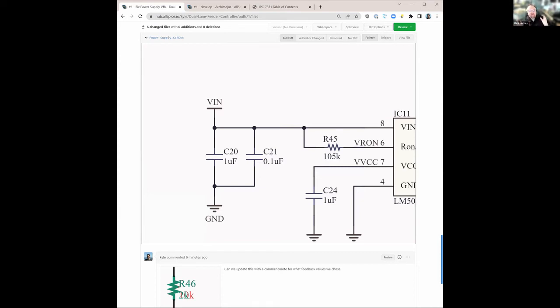It's great for designers because you get the latest, greatest, absolute everything. The stub drill distance is a little more accurate. You can do a little bit more of this. But then I go over to Joe's PCB shop, or I hope that's not a real company, I'm just trying to make one up, and he hasn't bought a new drill machine in 10 years or a new pick and place in 15. And you've got to adjust your design for the equipment that's going to be used to assemble it.